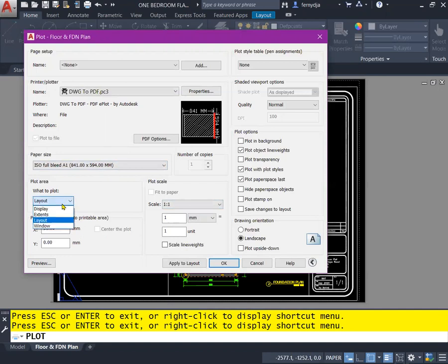But if I go to extents, and then click on center, what do you notice? It automatically works out what that margin would have to be. What's the distance from the edge of the paper? So you have the option to record these numbers and then come here, choose layout and put them back, but there's no need. But there's a drawback though.